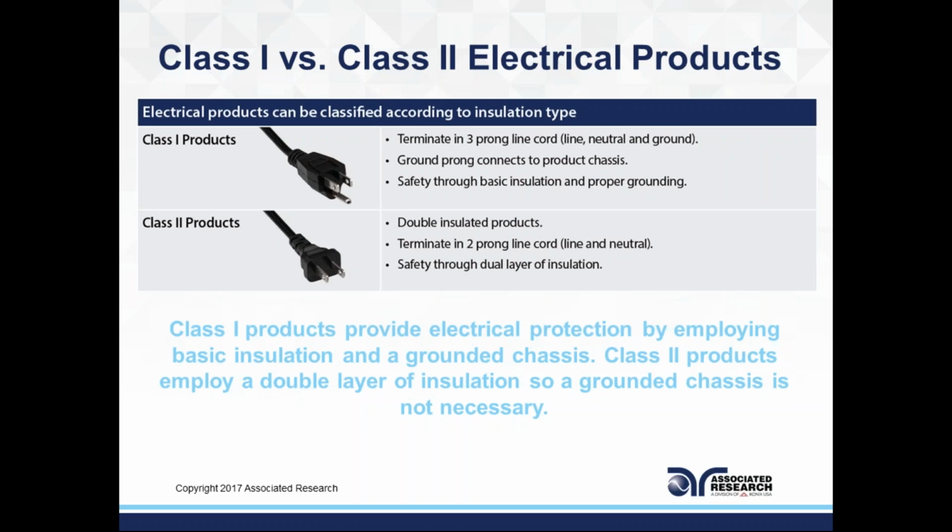Now, I mentioned earlier there are some products that you don't have to run continuity tests. Obviously, for Class 2 products, which are these right here, there's no need to run continuity or ground bond test since there's no ground circuit.